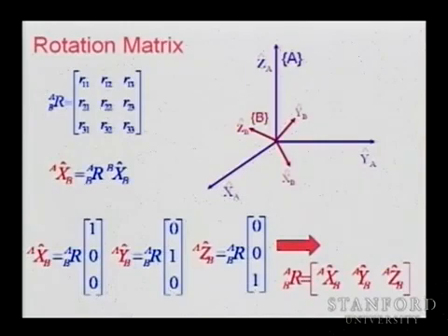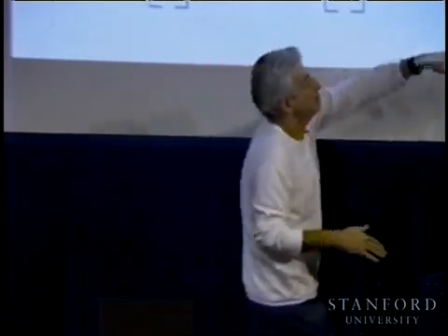This is very, very important because we are going to find the rotation matrix through many different ways. But sometimes you are looking at a problem and at the frames. Look at the components of that frame in the other frame, and you will make sense of your result. This is always the definition.